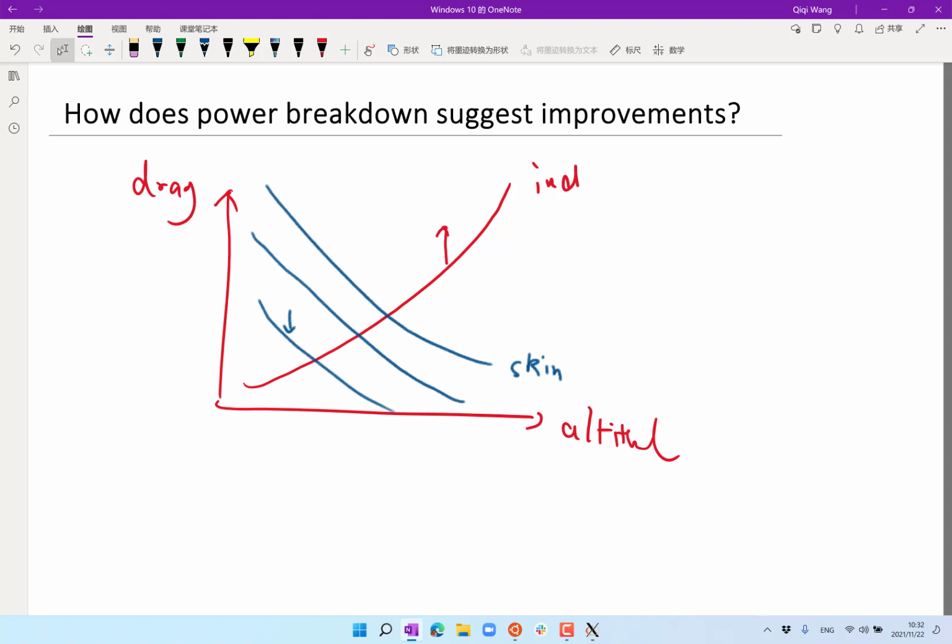And a huge portion of the backward swiping phase is at a negative speed. Essentially, the blade is going back, but the airplane is going forward. So a large part of it is going at negative speed. Only the tip provides any lift, and even that lift is much smaller because the speed is only a third, and the advancing side is already going at Mach 1.